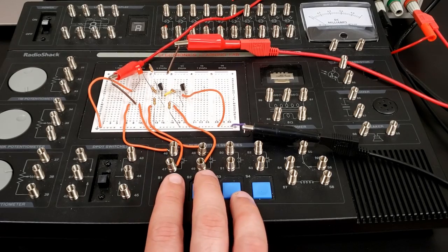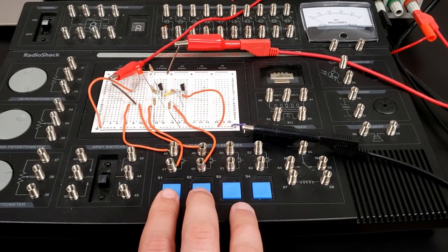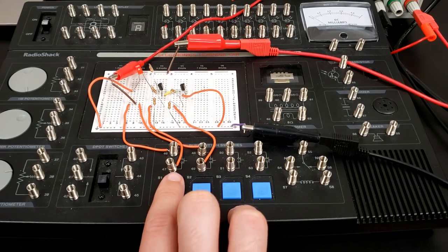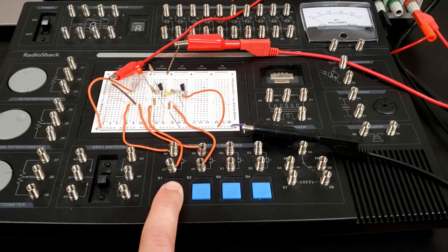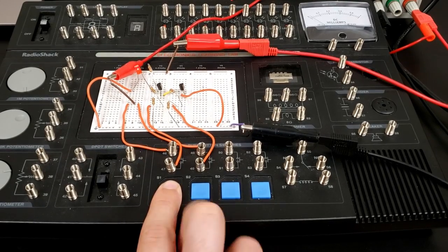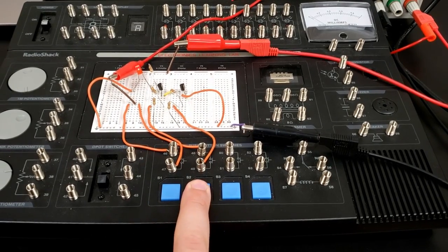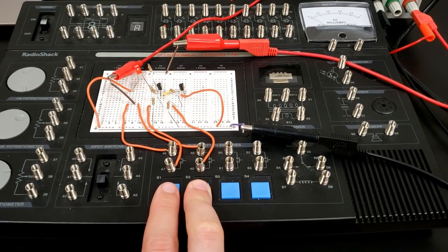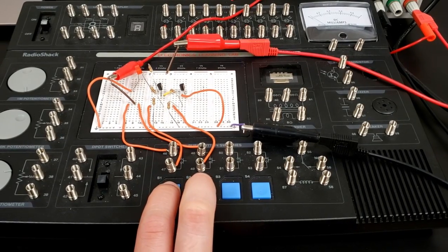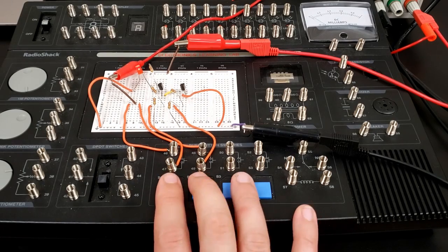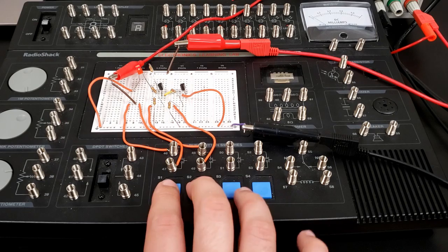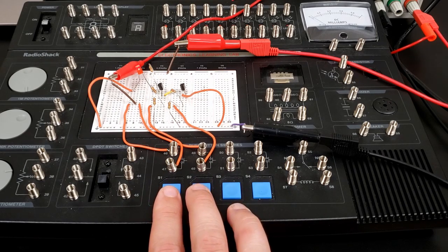You can see that the light is currently on even though both of these switches are open. Now let's close one of our switches. So we have the 1, 0, and you can see we still have an output. So a 1, 0 would still have an output of 1. If we do 0, 1, same thing, we have an output of 1. And if we press both of them at the same time, only then do we have no output. So this would be a 1, 1, 1, 0 output for those 4 different possible input combinations. This corresponds to an OR gate, as we talked about again in the introduction.